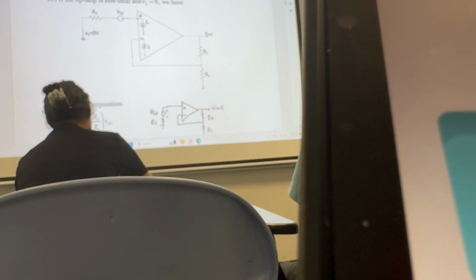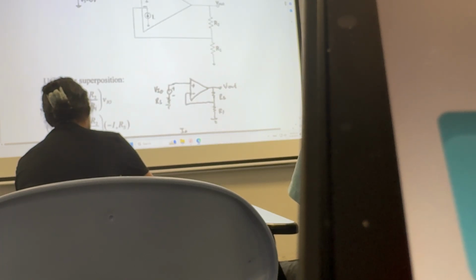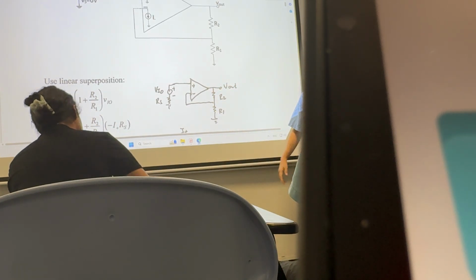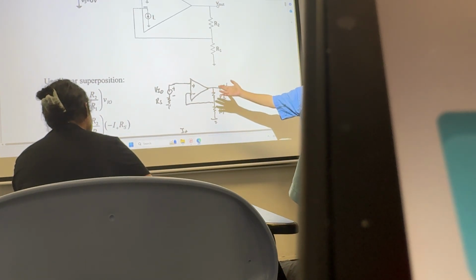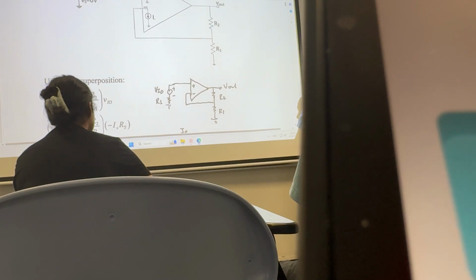Number one, right? We analyze this picture, only the offset source, Vio. We suppress all the bias currents. So very straightforward, right? No bias current because all the bias currents are suppressed, only the offset source. No voltage drop on RS, you directly amplify with the non-inverting gain. Next, consider I minus.